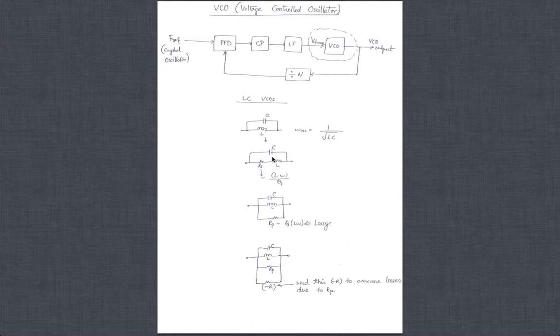But in reality, the inductors we make on-chip have finite losses. The series resistance is RS, which we represent by Q, the quality factor of the coil. Typically you could get Q numbers of 10, 12, 15. But with really good thick metal in the IC technology, at the topmost metals, you could even approach Q of 20 to 25. The bottom line is, the higher the Q, the lower the loss. A simple way to represent the loss is RS equals L omega, the reactance of the inductor, divided by Q. So the higher the Q, the lower the losses, and the better the oscillator.